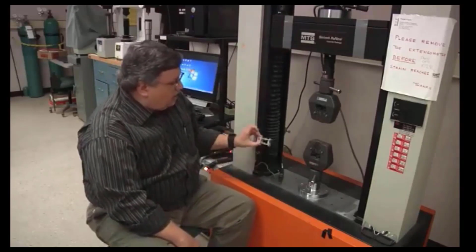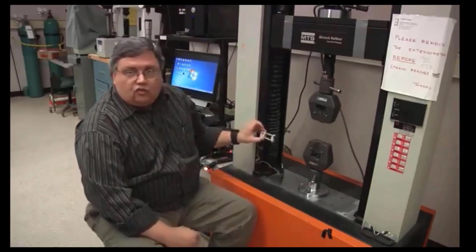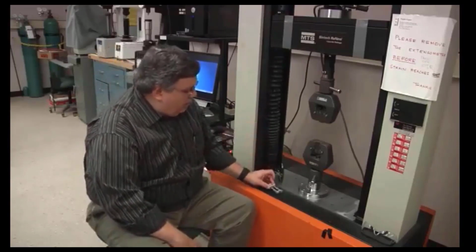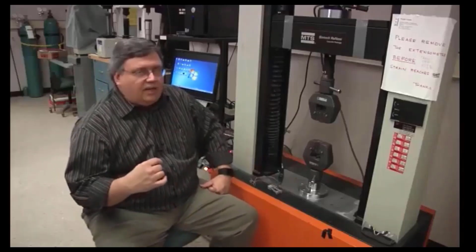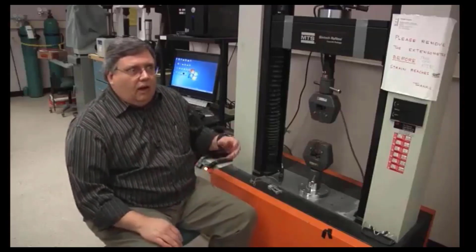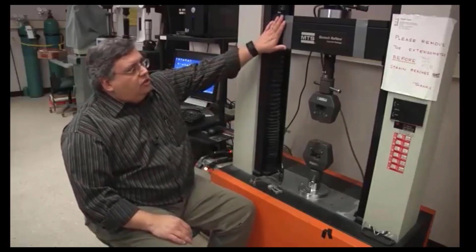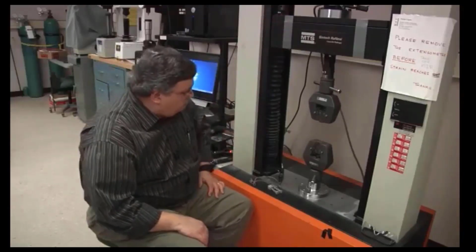And then with this extensometer, we can measure the actual stretch of the specimen during the early parts of the test. That's important because we need a very accurate measure of strain during the early parts of the test in order to get a good measure of modulus of elasticity. Once we get past the yield point, then stress is important, but strain is no longer as important to have an accurate measure, and so we just use the motion of the crosshead for that.